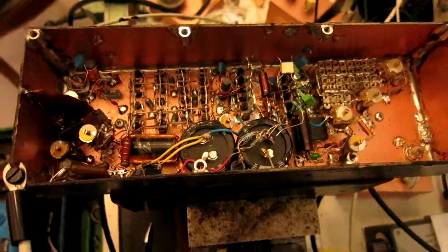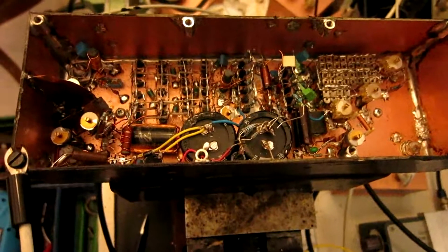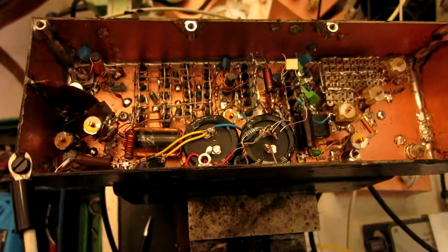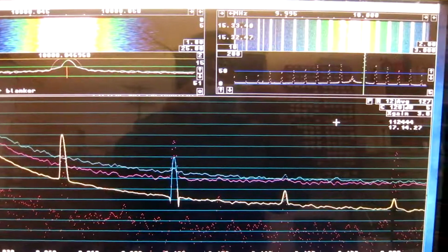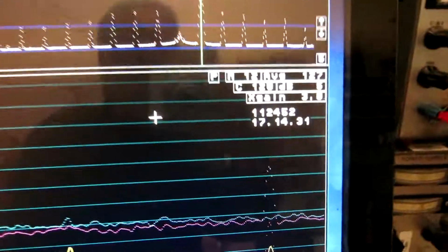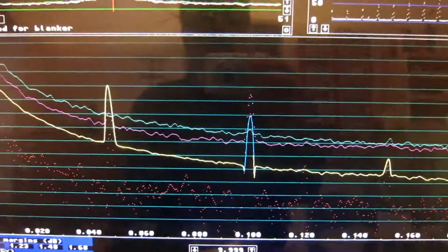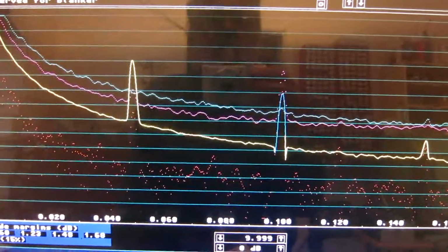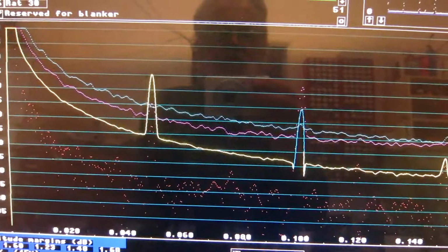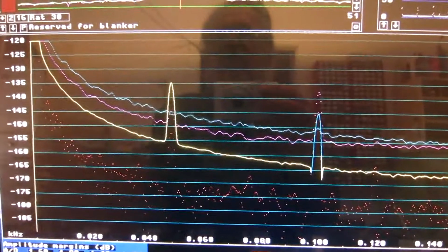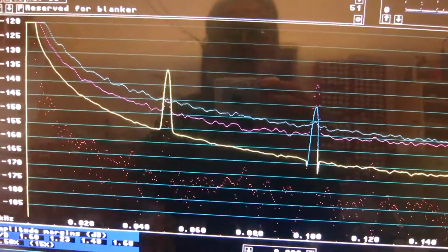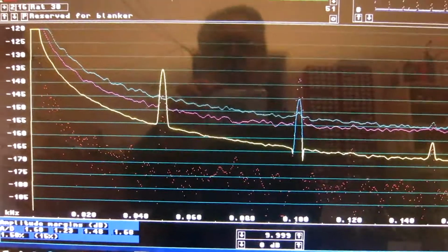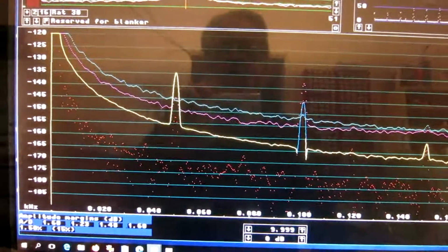In this video I will study the close range sideband noise of this selective amplifier, which I also use as an oscillator. It has been running now for 17 hours on my 2-channel signal analyzer, 2 receivers with correlation spectra of the phase noise. Look at the previous video for details about this. I will save this spectrum so I can evaluate the sideband noise levels.